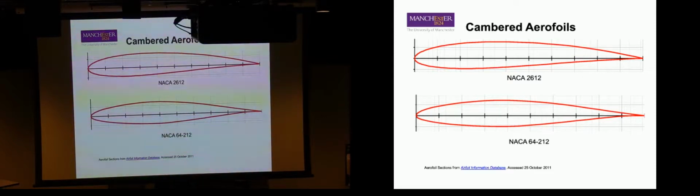That's why we have a tail, right? They want to turn down. And then the center of gravity is also in front of the neutral point. It may be in front of the aerodynamic center for the airfoil or the wing, which means the lift wants to nose down. So we have to counter for it more. What's bad about nose down pitching moment? What type of aircraft or configuration of aircraft would you not want a nose down pitching moment out of your airfoil?